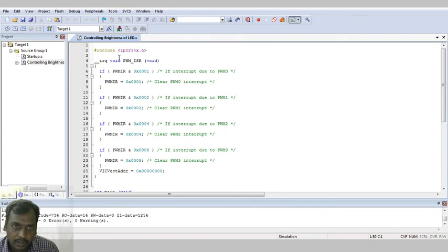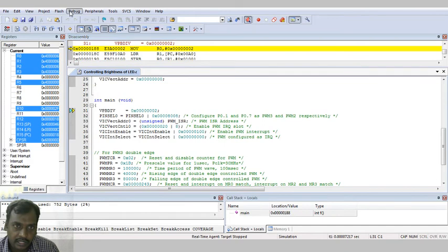Okay. So go to the debug menu and click on start debug session. The program code size will occupy 32 kilobytes. Okay. So here go to the debug menu again, run the command, observe the output. Okay. Port 0.2 and port 0.7. Observe this output. Here continuously T on, T off.